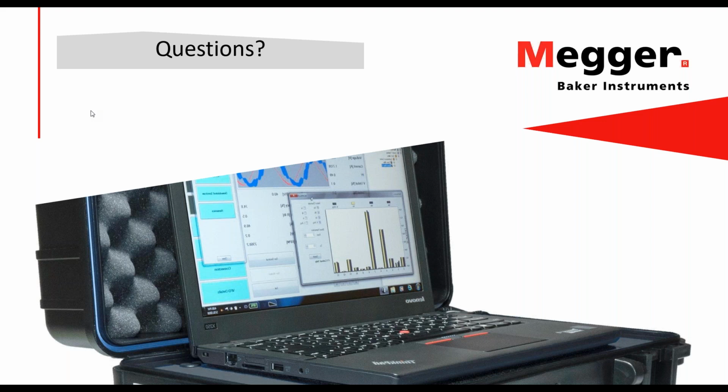Over to Abel. Do I have to know the number of rotor bars for rotor spectrum testing? Actually, you don't. The more information you have about the motor that you are testing, the easier it would be for you to interpret the results you're getting. So if you know the number of rotor bars, then it's better for you. You have that information in your hands when you are analyzing the results. But the results that you get do not rely on knowing that information.